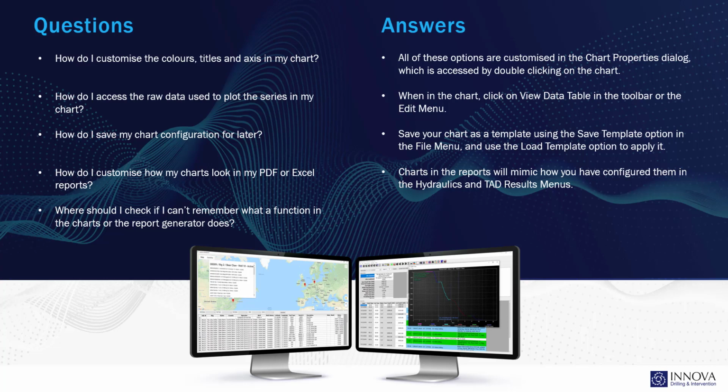Finally, question 5, where should I check if I can't remember what a function in the chart or the report generator does? The best place to look is in the help file. So the chart section will describe all the functions inside the chart. The file menu contains the functions for the report generator. The tools menu covers the pump data, and then the options menu covers the drilling data, the pressure gradients, and the pipe tensile yield limit.